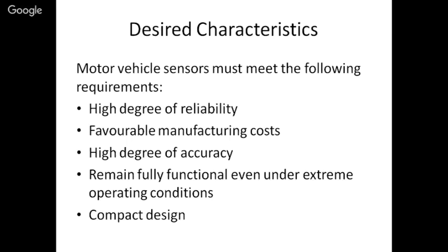So our ECU is constantly monitoring the RPM of all the wheels. So if it finds that one particular wheel is decelerating at a higher rate as compared to other wheels, it will immediately reduce the braking effort on that wheel. So we may have pressed the brake pedal, but that is only a signal that goes to the ECU. The rest of the thing is done by the ECU. We do not have any manual control over our braking. So that is why the first point, high degree of reliability.